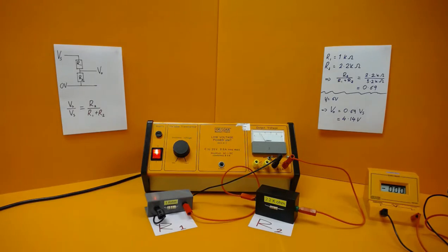Applications of resistors, potential dividers. Resistors may be used to obtain different voltages from one supply. The arrangement of resistors is called a potential divider. The value of the resistors may be chosen to give any value of output voltage, V0, between 0 volts and the supply voltage, Vs.